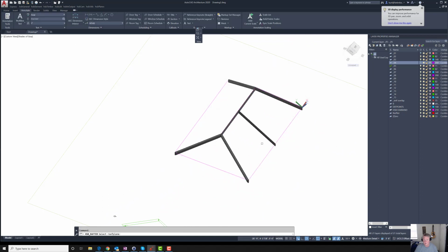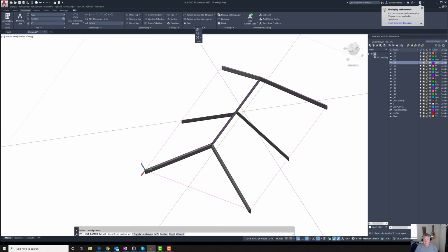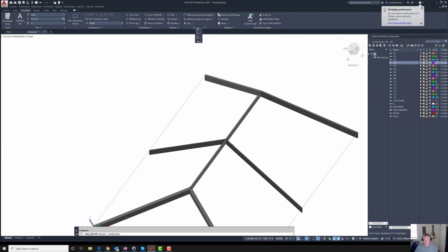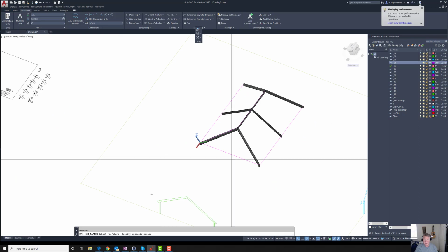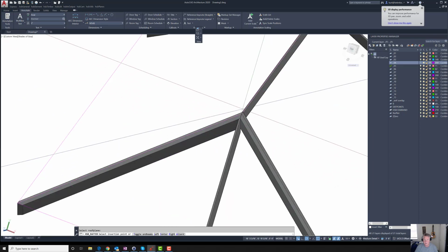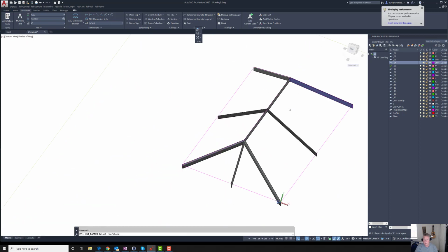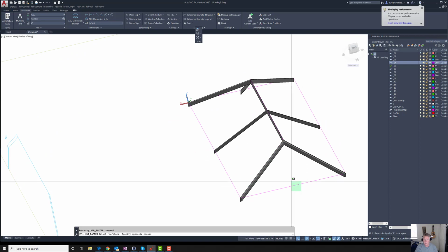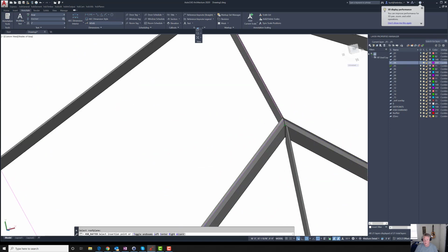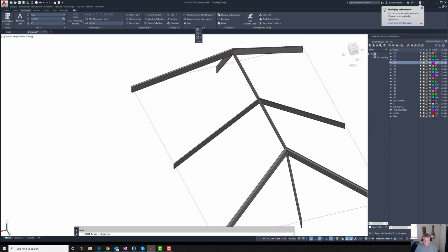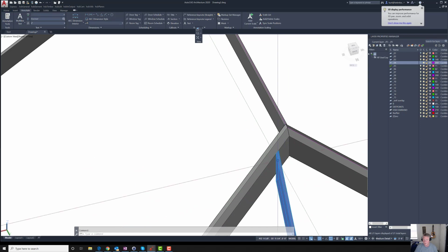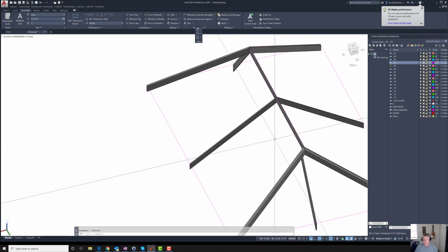I'll just snap it to the middle of everything. We'll do the same thing on this side over here. This is our common rafter for the 8 and 12 pitch. I'll do the same thing over here. We'll maybe center our layout if we want that, and on the other side, just for fun, we'll do the same thing, but then I can move that rafter. We'll just go 8 inches, and you can see that it's automatically readjusted itself to be cut flush to the face of the hip.